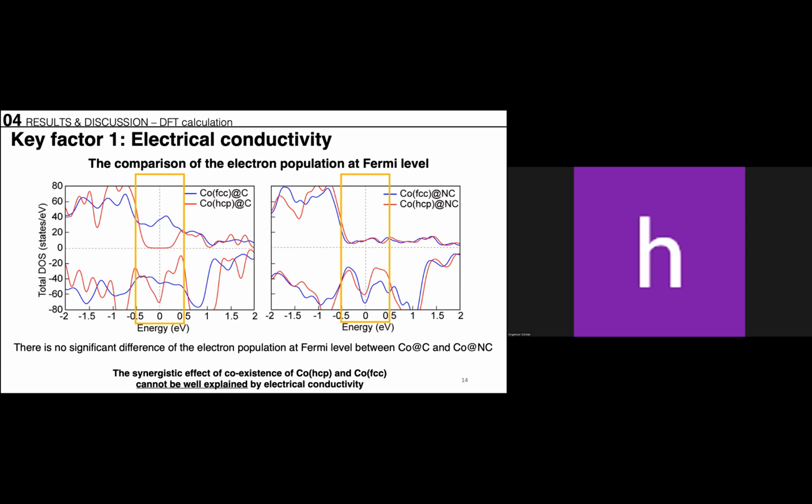Did you consider only the cobalt in both phases and see if a certain phase transition can occur in the condition? You have to check first if the phenomenon occurs already in the metal, and then see what happens when you consider interfaces. So my question was, did you also study the problem only for the metal in the two polymorphs, FCC and HCP? Maybe you can check the transition between the two phases, and the stability of the phases. If there is some study by you or other groups.